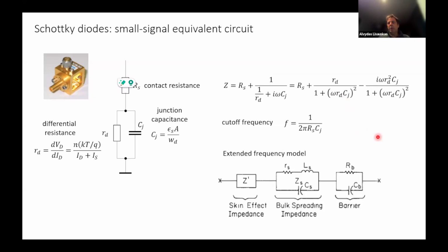So in Schottky diodes, there are additional phenomena when going to higher frequency and pushing the limits of frequency more and more above the microwave frequency range. One has to take into account that the junction becomes, so we start losing that 3D character of the transport, and it becomes more and more related to the surface.